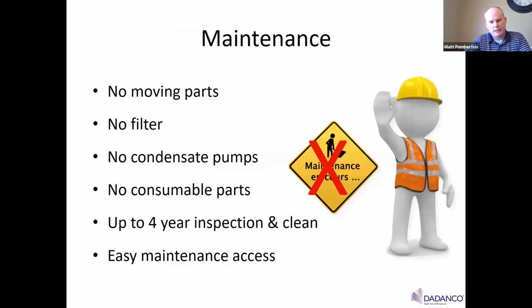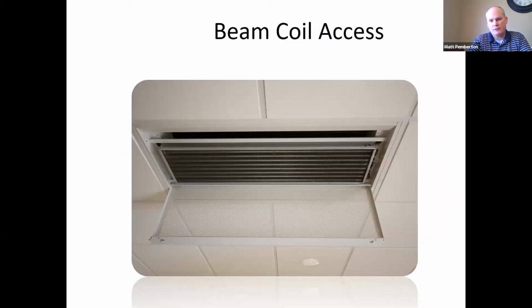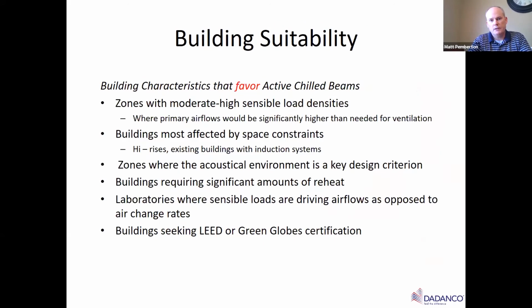We talked about low maintenance. Again, this says every 4 years. I recommend 2 to 3, but sometimes people go further than that. It's a dry coil, so it's very easy. Again, no fan, no filter, no moving parts, drop down an access panel, and there's your coil to clean.